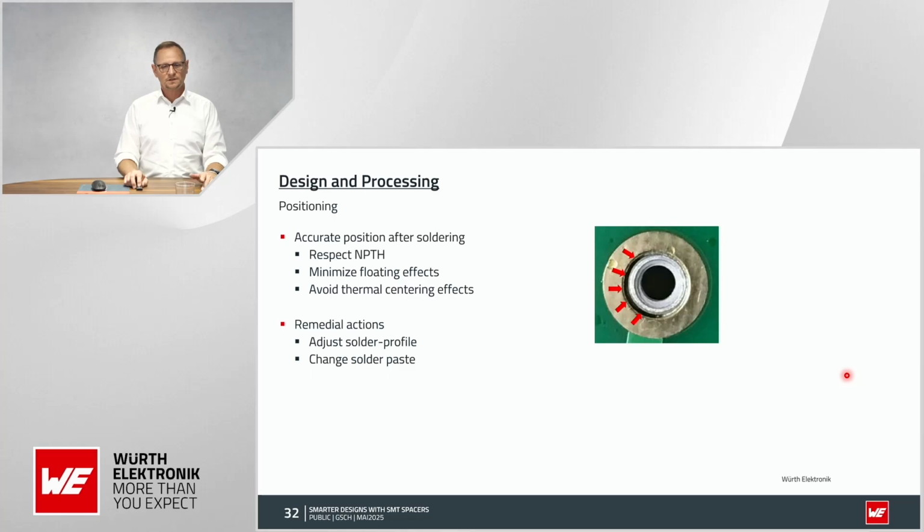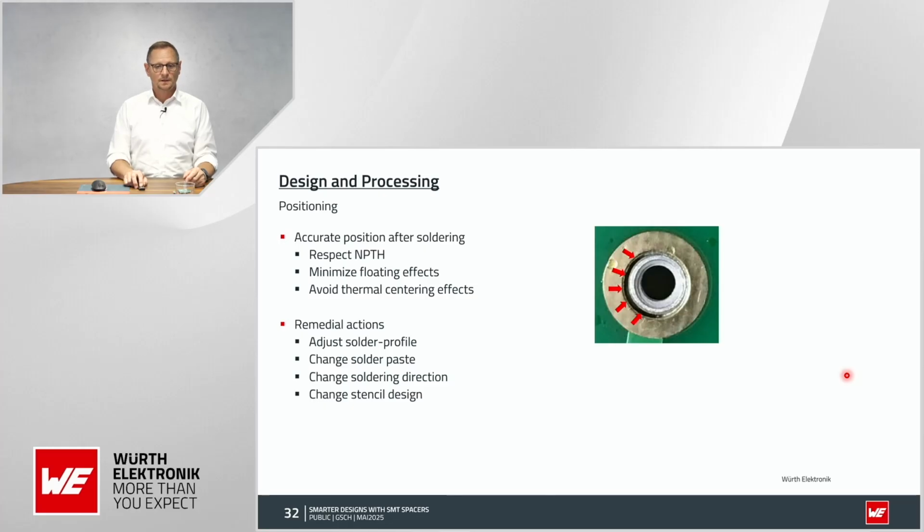So what you can do is adjust the solder profile, change the solder paste. Maybe you have a chance to test with a different solder paste. Then change the soldering direction. Maybe it makes a difference if you run it this way, or if you just turn 90 degrees or even 180 degrees, and then you might get a different effect. You can also change the stencil design. You can narrow it a little bit, then it cannot move so far.